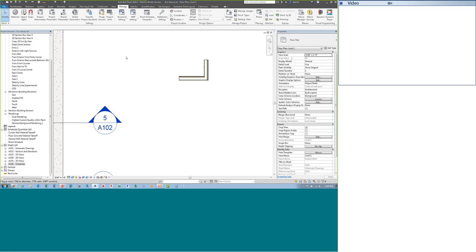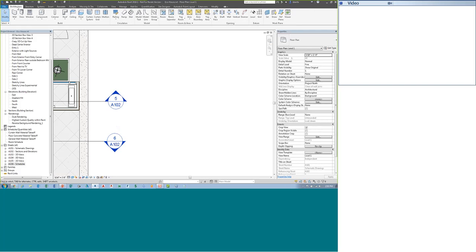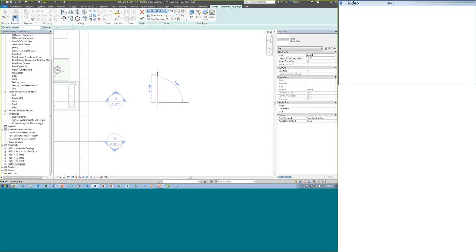And then another way that people use it is, let's say you have a floor that you want to create, and you're in sketch mode, and you're drawing the floor lines like this, not a big deal. And then you realize, oh, that last line that I drew is not really what I want. If I do Control-Z to initiate the stop of the next segment, and then do Control-Z again, it will keep reducing and removing the previous line work. So that's really kind of like an undo within the sketch mode.